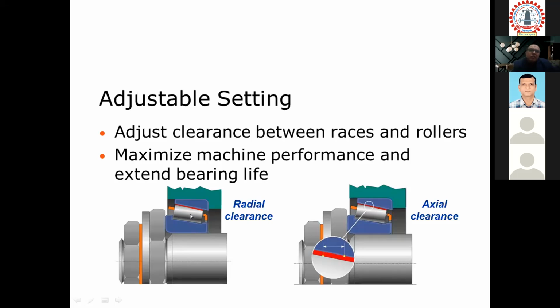So that vibration analysis or condition monitoring system will be able to tell us which component has started wearing out. So when you are recording that reading on a regular frequency, let's say every week or every month, then over a period of time, you can decide and plan your shutdown for the plant to do the bearing maintenance.